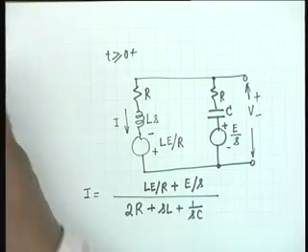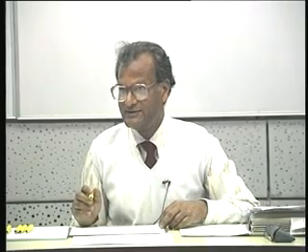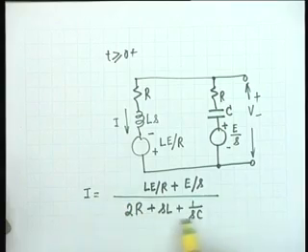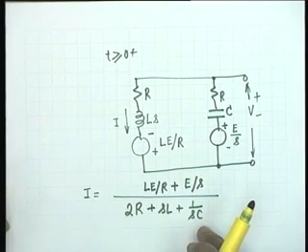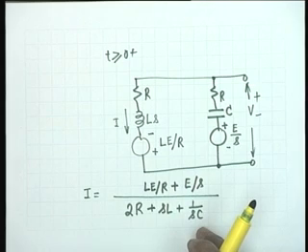And if you simplify this with L equal to CR squared, normally this looks like a second order circuit, and therefore the denominator, after clearing fractions, after clearing the inverse power of S from 1 by SC, should be a quadratic, agreed.